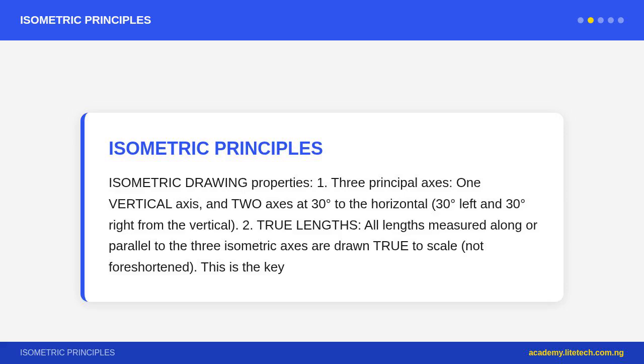Step 5. Complete the box. From the top of the vertical edge, draw parallels to the L and W edges. From the ends of L and W edges, draw verticals. Step 6. Show visible edges as solid lines, show hidden edges as dashed lines, or omit hidden lines for clarity. Important, use a 30 to 60 degrees set square with the T-square to draw the 30 degrees axis precisely. The vertical is drawn with the T-square and a set square at 90 degrees.